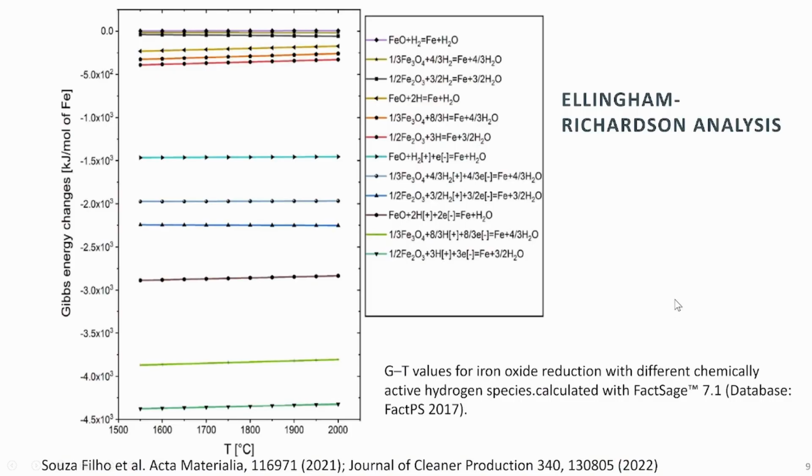And when you want to better understand from an equilibrium standpoint how this acts as a reductant and how efficient it is, you would plot the corresponding Gibbs free energies, as you see here in a so-called Ellingham-Richardson diagram, where you balance out the free energy of the corresponding oxides and the corresponding driving force you receive from the reduction by using such radicals or other reductant gases.